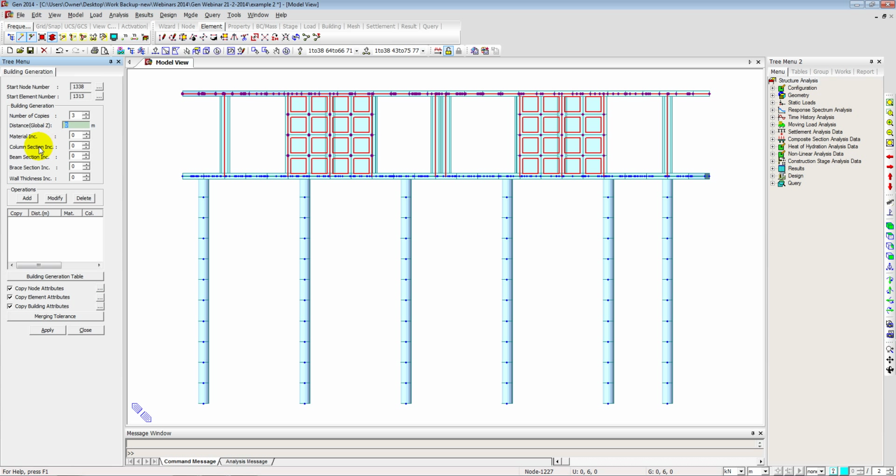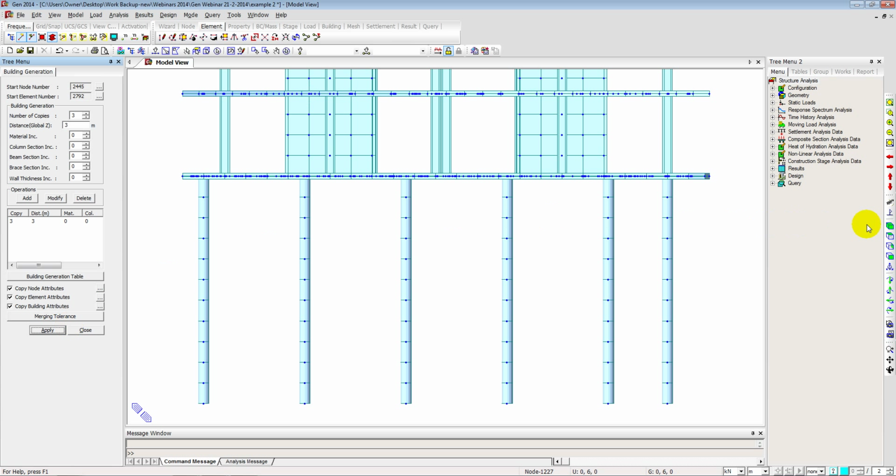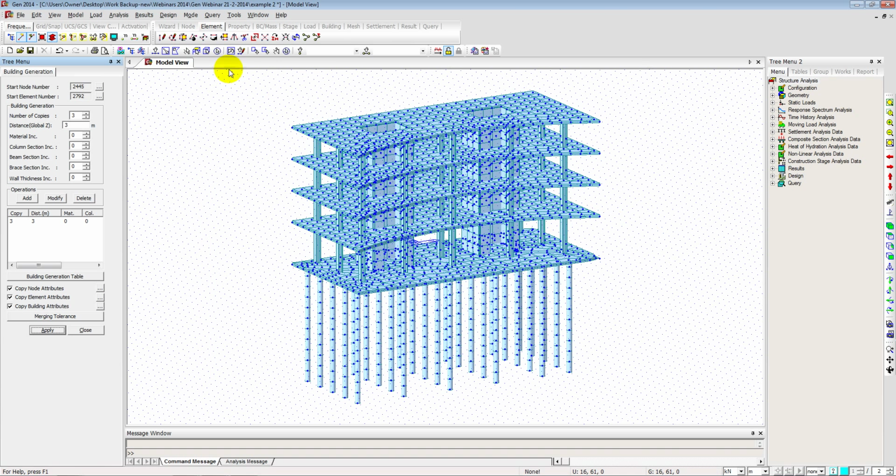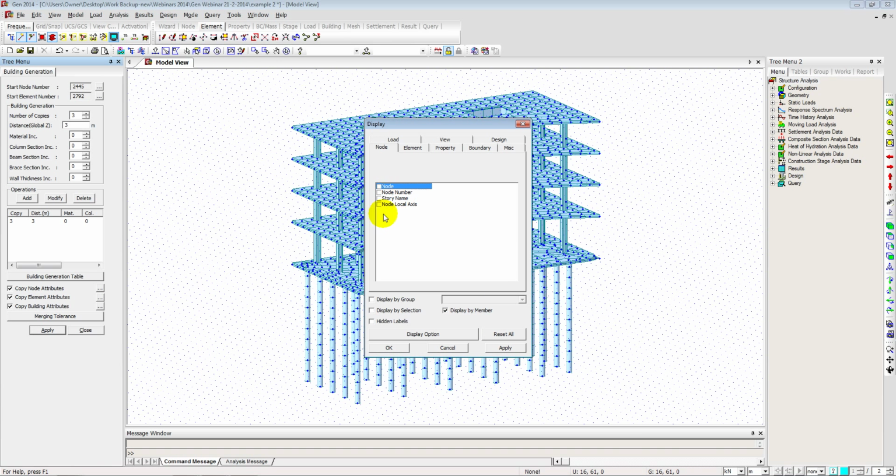And then we just want to make sure that the additional floors are 3 meters high rather than 4 meters high. So we've got the lobby area to be 4, and then the remainder of the floors to be 3 meters in height. So just add that, and then click apply. There you go, and there's the whole building that's been generated. That's 4 floors going up through.